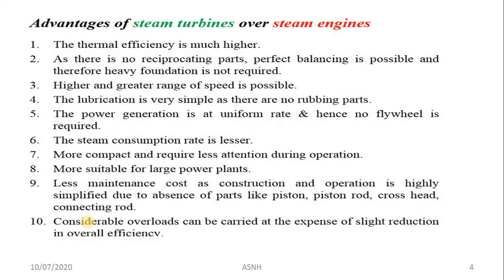So these are the advantages of the steam turbine over steam engine. So students, steam engine is also one kind of the prime mover, but how it differs from the steam turbine, here we will discuss. The first advantage is that thermal efficiency is much higher. Second one is, as there are no reciprocating parts, perfect balancing is possible in case of the steam turbine.